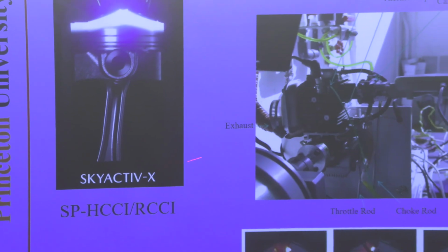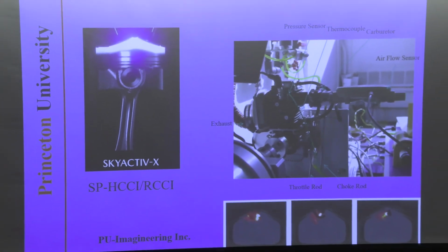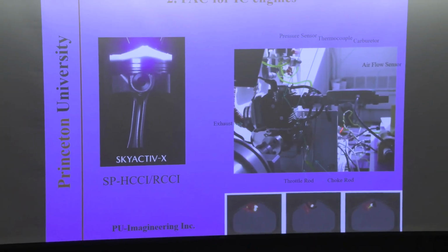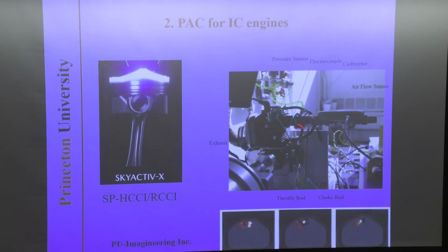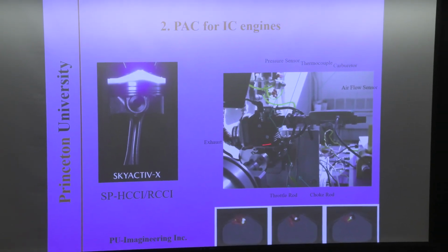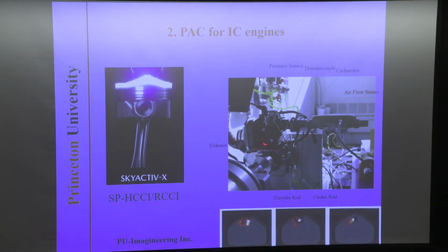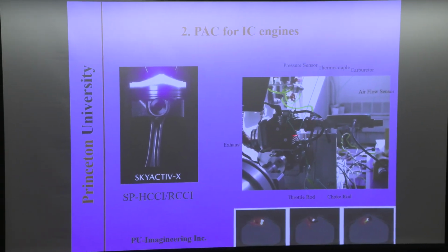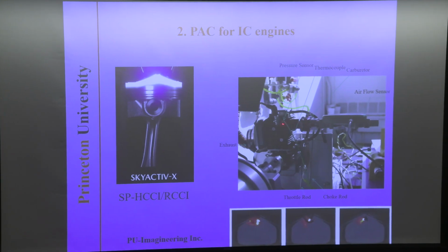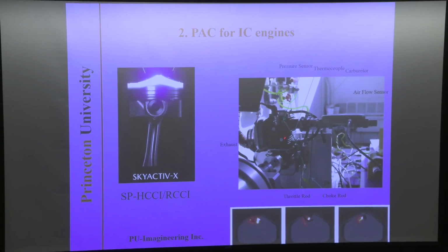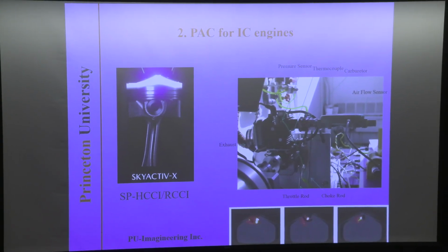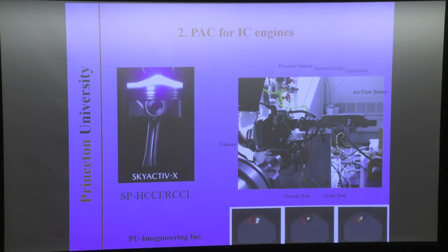So then this is about high-speed propulsion and the internal combustion engine. A few years ago, the Air Force wanted to look at UAVs with internal combustion engines. This UAV is very small, probably only a 35 milliliter engine size. They are so small that they can only operate at fuel-rich conditions, because at nearly stoichiometric or fuel-lean conditions, the engines start to run very rough or even fail.